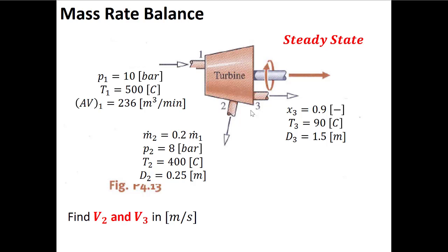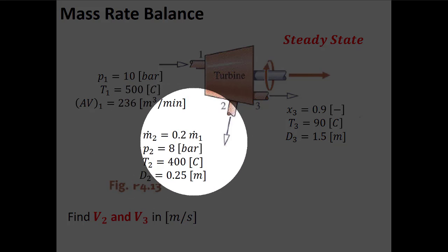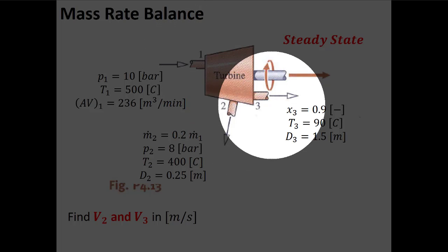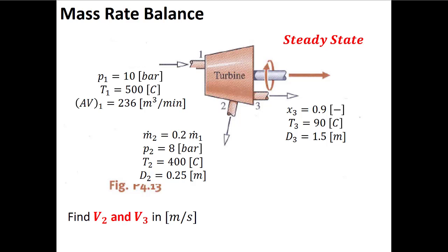So now I look at this problem, and I've got to think, I know this is a conservation of mass problem, right? But I have to think, what version of conservation of mass are we talking about here? First, it's maybe a bit of a hint that we have mass flow rates here, but maybe not necessarily, because you can have an elapsed time where you say, oh, we have a mass flow rate and some unit of time, like an hour, how much mass left the system? So we do have a mass flow rate, which maybe makes me think the rate equation. I also have different ports here that are at different positions in space, right? But I'm not exactly sure.